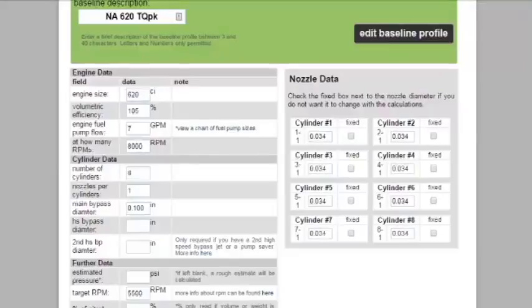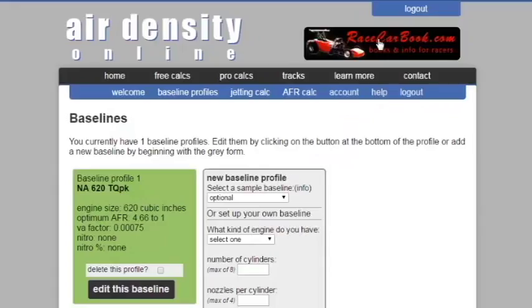4.9 to 1. Well, what I'm going to do, knowing that this is a little on the lean side for tractor pulling, is I'm going to richen this a little bit, and I'm going to go to a 95. And that's about 4.6. That probably would be a more reasonable number in tractor pulling, whether you're under enormous load, especially an engine this big. On the other hand, if you have a really good cooling system, you may want to get it back up to that 4.9 to 1 air-to-fuel ratio.